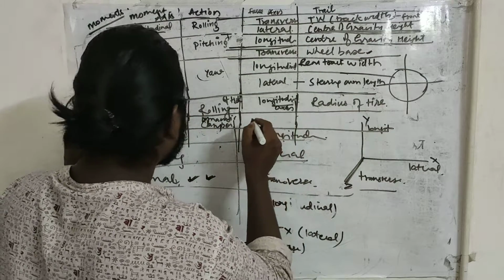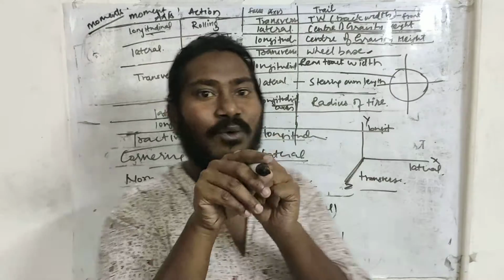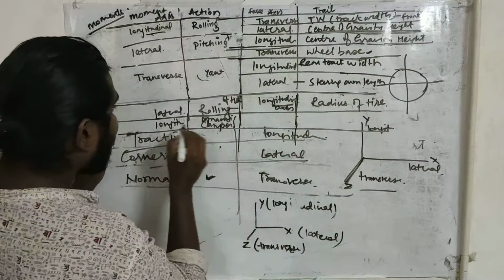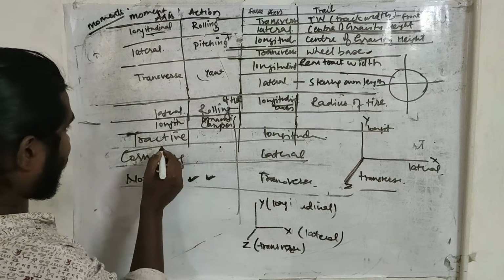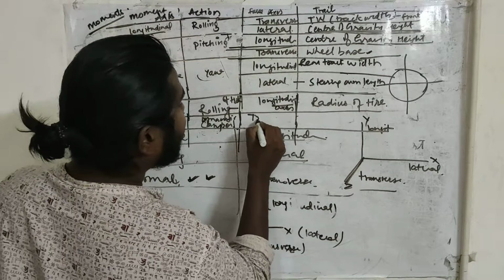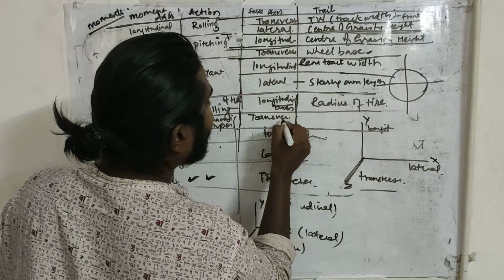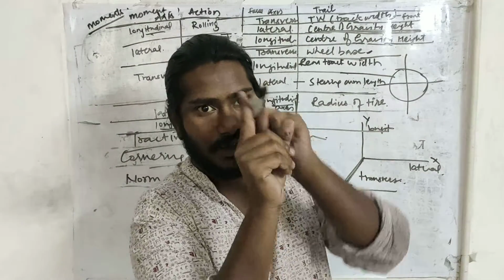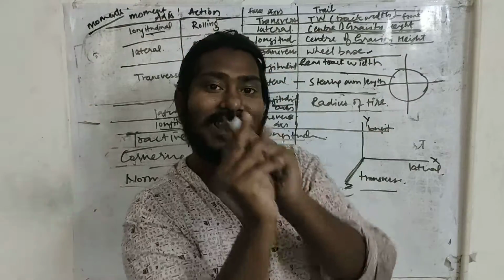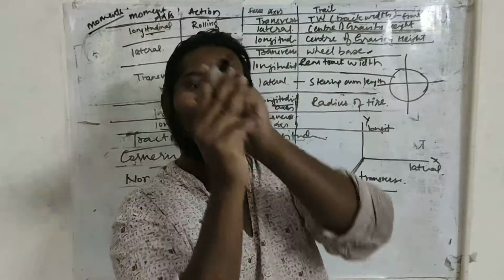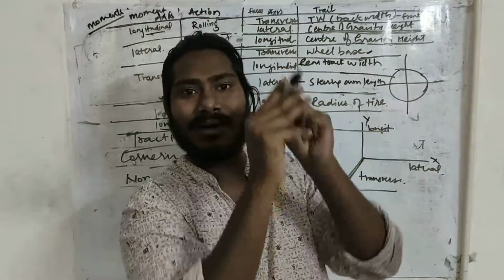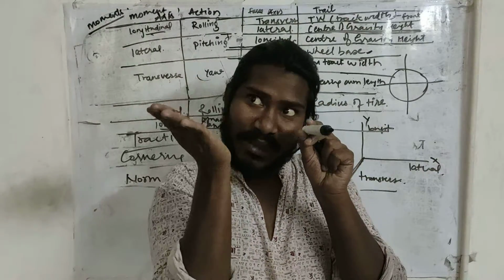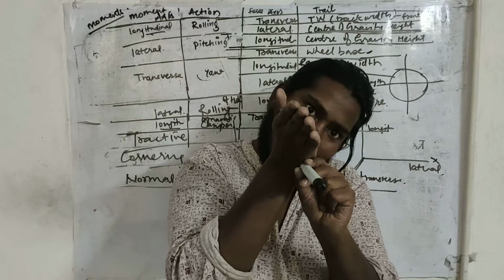Camber. Force axis. What is going to be the force axis for the dynamic camber change? The normal force, along the transverse axis. This normal force is making your tire go for camber in or camber out, a positive or negative movement on the axis that is being translated to the tire.